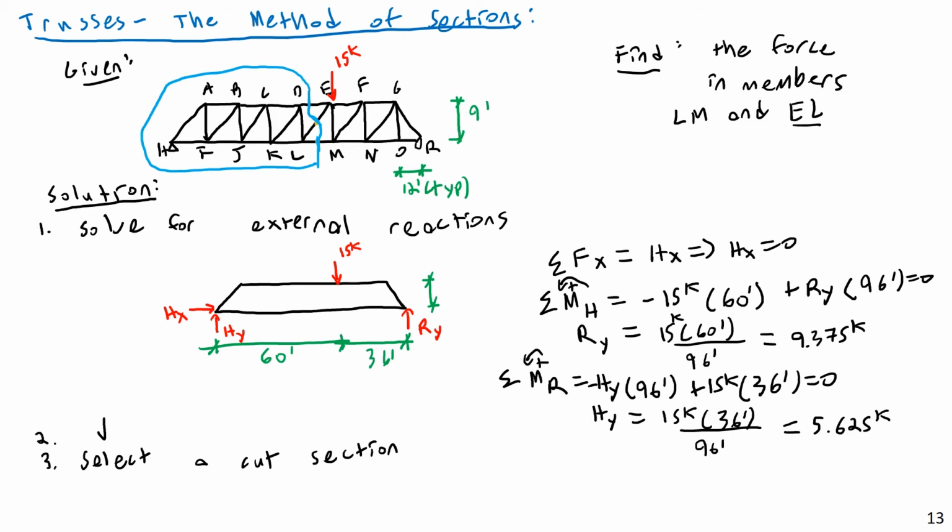It could be done and it wouldn't be that difficult, again, in terms of just raw math. There's not even an integral in there at all or anything like that. Literally just basic geometry and trigonometry. But again, it's very tedious to work through all of those joints. What we've been able to do instead with the method of sections is that when we're looking for this internal member force, we can just cut out an entire section of the truss, just an entire giant chunk of it, and look at what forces are in that member directly, which can be very useful.